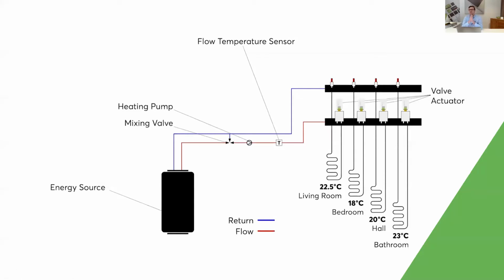And the mixing valve then actually mixes the return water back into the flow to adjust the flow temperature. And that can massively, massively increase the efficiency of your heating system, because for most heating sources, gas boilers, electric sources, heat pumps, their most inefficient time is when they first start. So if we can keep this running for longer and just mix some cold water into this 62 degrees outflow to make this down to, let's say, 30 degrees, because that's all it needs, and the boiler's then modulating itself, we will save quite a lot of money over the course of a year.